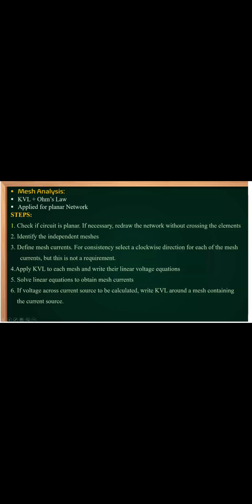The next concept is mesh analysis. Mesh analysis is KVL plus Ohm's law. I told already, mesh analysis is applied only for planar networks. For non-planar networks, we don't apply mesh analysis. But for planar networks, you can apply both nodal analysis and mesh analysis. Both are applicable. But mesh analysis is applicable only for planar.